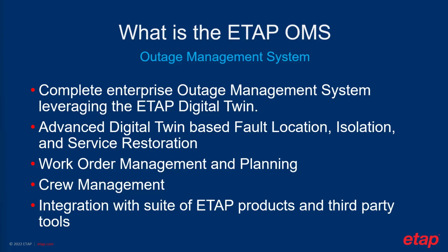It's an advanced digital twin based fault location, isolation, and service restoration solution, meaning that we can identify where the fault is with minimal inputs from the field and then provide a switch plan for which switches to open and to close in order to partially restore as many customers as possible, and then eventually, once the fault is cleared, to restore all the customers.